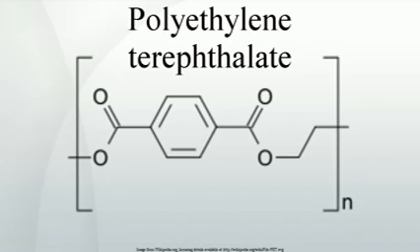acetaldehyde. When acetaldehyde is produced, some of it remains dissolved in the walls of a container and then diffuses into the product stored inside, altering the taste and aroma. This is not such a problem for non-consumables, such as shampoo, for fruit juices, which already contain acetaldehyde, or for strong-tasting drinks like soft drinks. For bottled water, however, low acetaldehyde content is quite important, because, if nothing masks the aroma, even extremely low concentrations, 10 to 20 parts per billion in the water, of acetaldehyde can produce an off-taste.